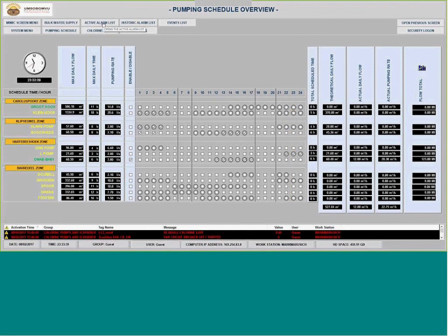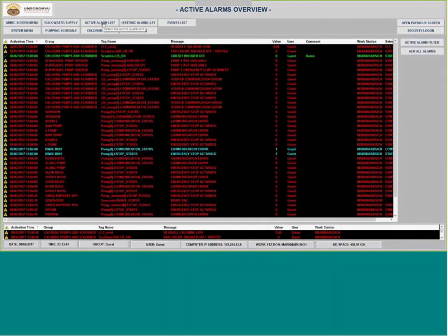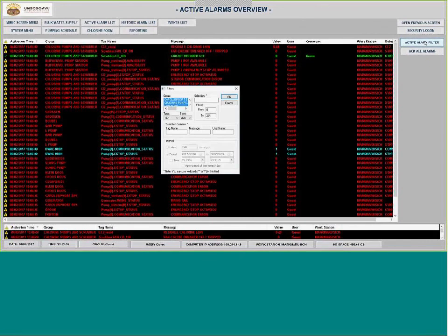We also have a look at the various alarms. We look at the communication status between the main station and all the different outstations, being the boreholes. We also implemented what we call an alarm filter, which is a little built-in function within InduSoft, where we can filter things.